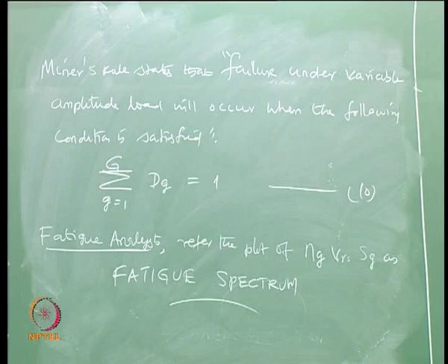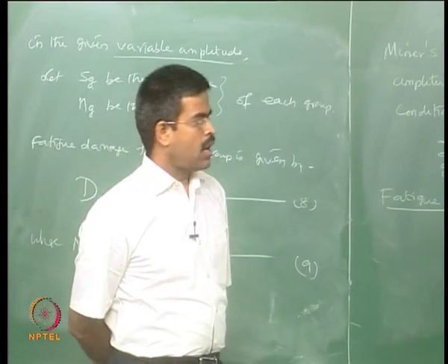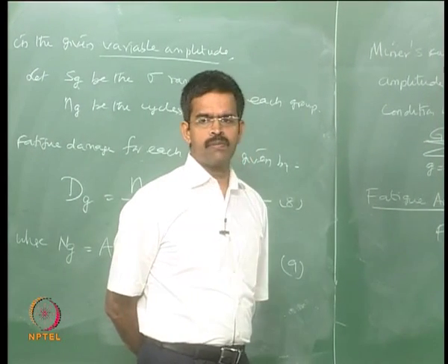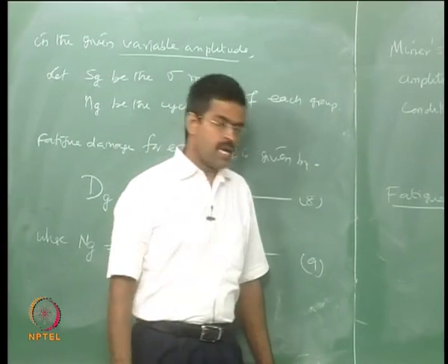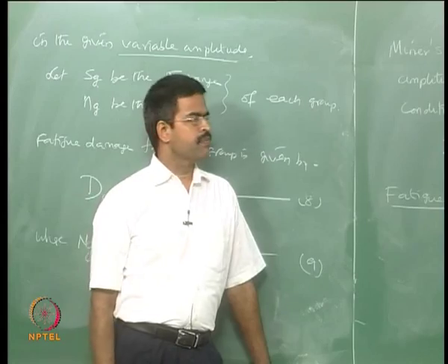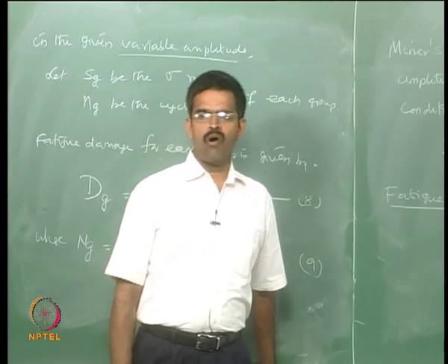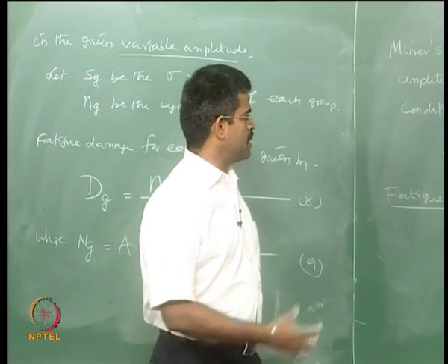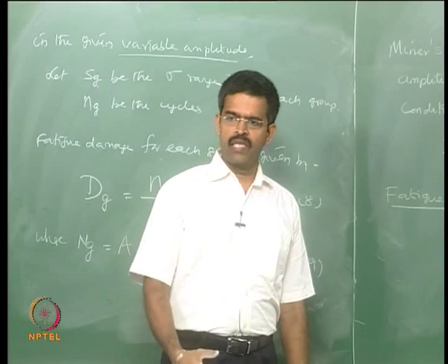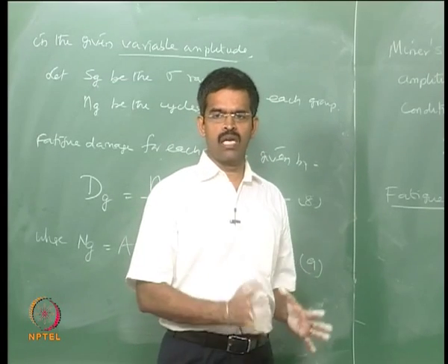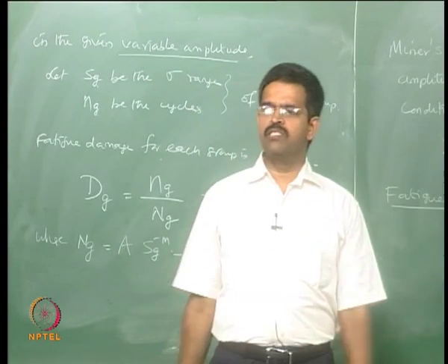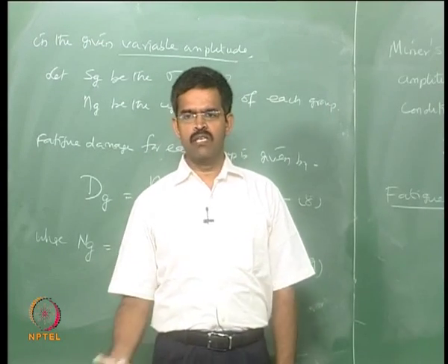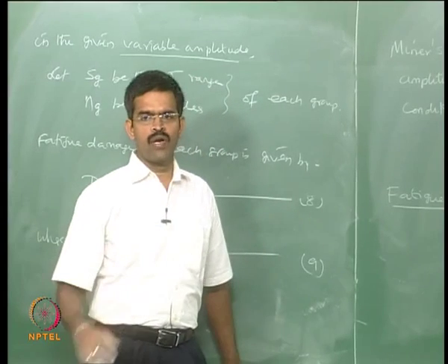So, in this lecture we have understood how the fatigue assessment or the fatigue failure on marine structures can be estimated, and why SN curves form a very major part in estimating the fatigue life of a marine structure, even though a marine structure can be constructed with steel as a material, which is similar to that of machinery, where endurance limit is always considered as one of the criteria to find out the cutoff stresses,